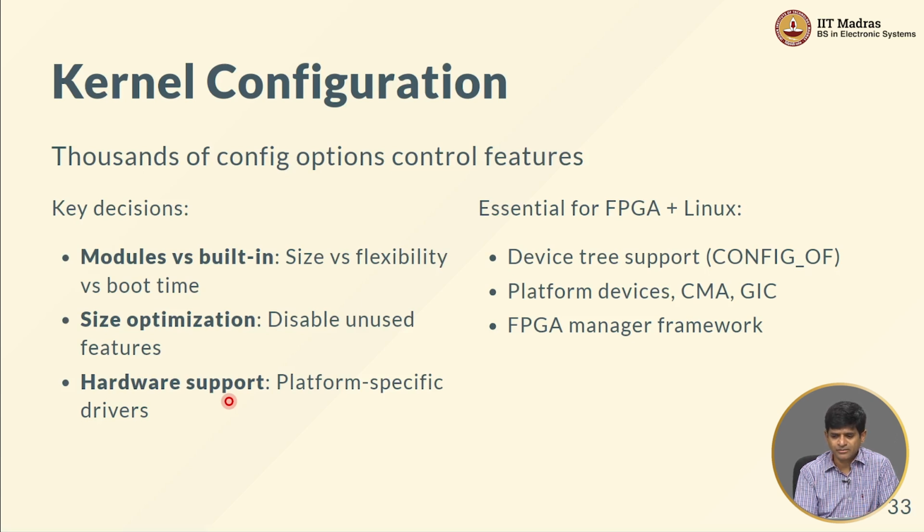Now in the context of FPGAs and Linux, there are a few options that are typically mandatory. One of them is just the basic device tree support. But apart from that, the whole approach of using platform devices, because that gives us the ability to use the platform drivers, which as we have seen are a very flexible way of implementing device drivers.